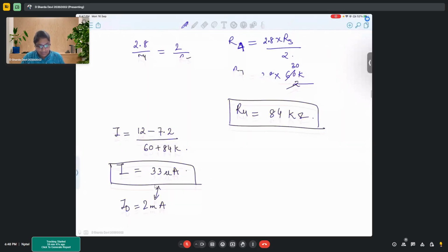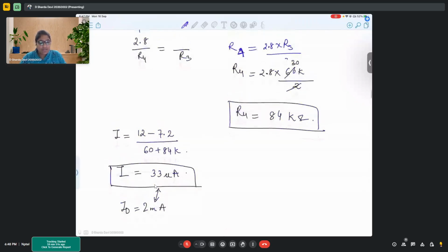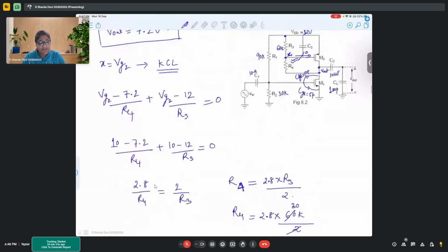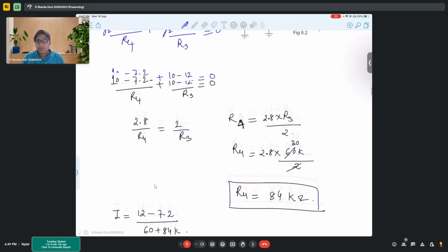And also, it is a rule of thumb while designing that you make sure that all the circuits other than your MOS transistor circuit have less than 10% of total power dissipation. So that is the idea. You should not lose much power in your supporting circuits. This is clear? Right. Yeah. Got it. Yeah, okay.